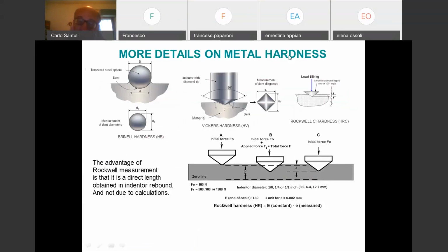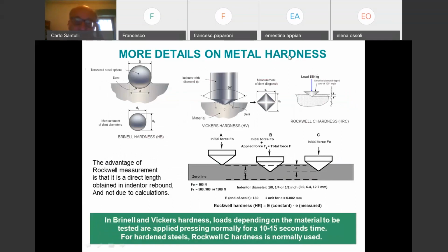And hardness, to complete what we were saying on hardness. Well, this is not complete because you will have then the hardness testing on plastics and on ceramics. We have different ways of measuring it. Basically, hardness is a technological test. It's not a mechanical, because you have empirical scales. I've shown you before the Brinell hardness, and the image referred to Vickers hardness. So Brinell is with a steel ball, Vickers it's with a diamond shaped tip.